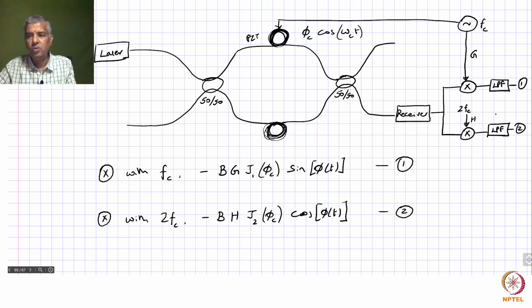On the other hand, if you know that the acoustic signal that's incident on this hydrophone is going to be at 100 hertz, let's say, then instead of a low pass filter, you can actually use a band pass filter. Okay, and then just pick up that 100 hertz component, or even better, you can beat it with FC plus 100 hertz or something like that, and then you can extract the specific component corresponding to FC and 2FC, which will correspond to 2FC plus this 100 hertz or 200 hertz, those components, and then you can extract the specific frequencies of interest for us.